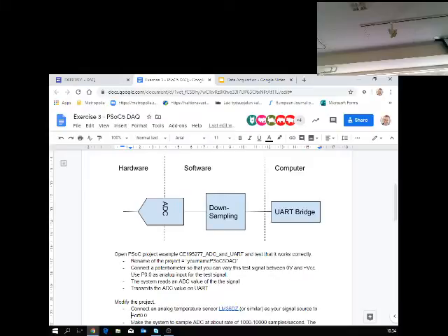The simplest way, which I recommend, is just to calculate the average value over a certain time. Sum every single measurement that the A to D converter has done, and at certain rates calculate the average and start over the summing. And the average is something that you will be sending.